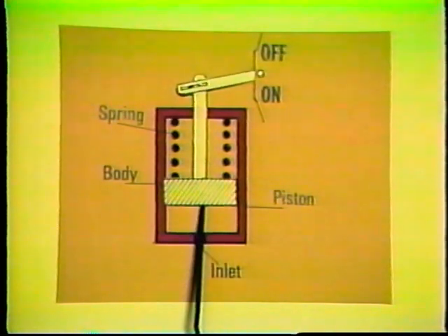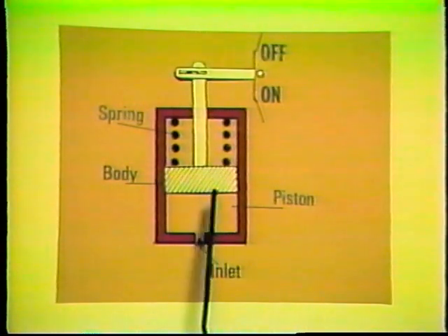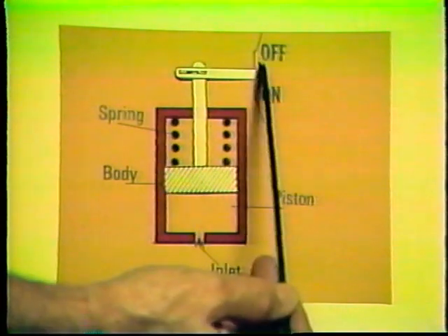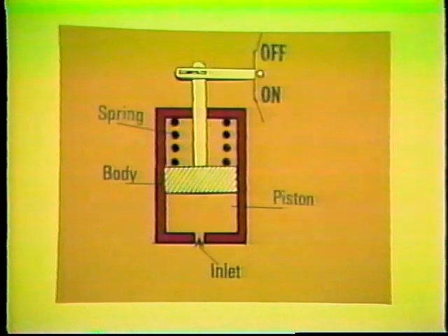The air pressure pushes the piston up, thus compressing the spring. When the air has reached a high enough pressure, the piston has moved so the electrical contacts are opened, and the electric motor and the compressor are shut down. The use of pressure switches like the one we just described is common for most small compressor applications, say in the 1 to 10 horsepower range.